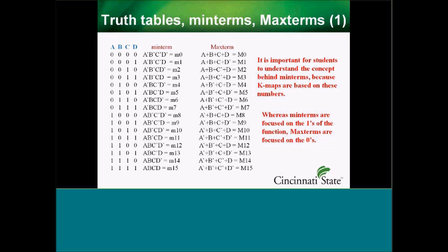Also, when we start moving over towards K-maps, the K-map cells are referred to by their minterms. This is something that I've worked with the students on quite a bit. Some people don't cover it. I do, and I think it's very helpful.